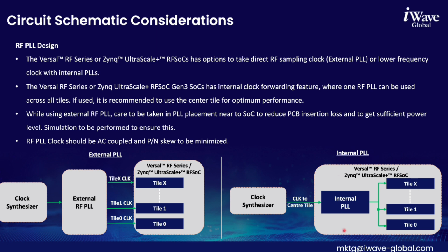When we use the internal PLL, we don't have to give a high frequency clock externally. We just have to give a low frequency reference clock to the center tile, and the internal PLL can distribute the clock to all the tiles.